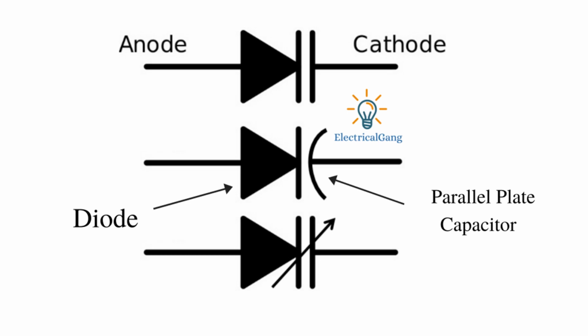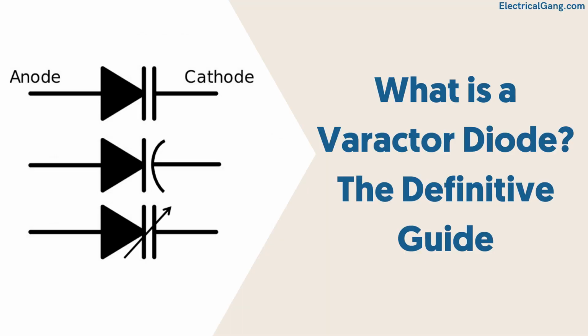Phase-locked loops, PLLs, are feedback control systems that compare the phase and frequency of a reference signal with a feedback signal. They can be used for precise frequency synthesis, tracking, and tuning in various applications. Frequency synthesizers generate output frequencies that are multiples of a reference frequency. They are used to generate specific frequencies required for various communication standards and protocols. Mechanical tuning elements: in some applications, mechanical components such as variable capacitors or inductors can be physically adjusted to change the resonant frequency of a circuit.